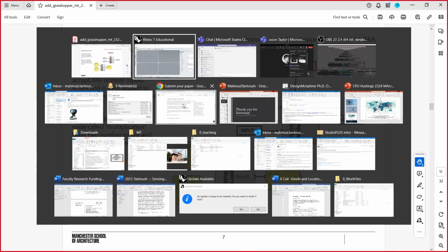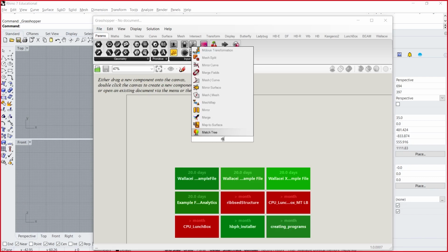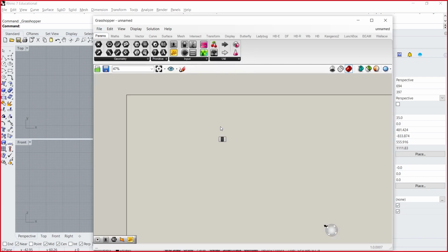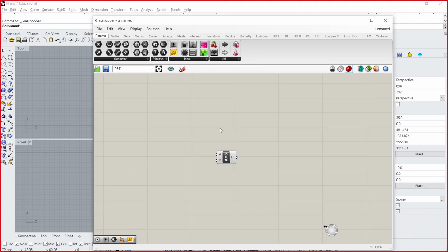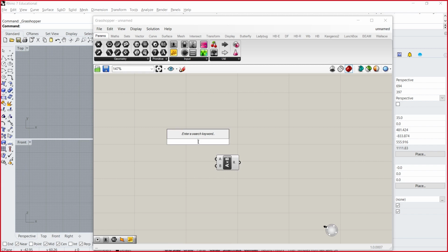So you can see here, yeah? Very simply. So I'll show you quickly here, just to drive it home. You can follow me if you want. So if I double click on the canvas, type in multiplication, and then double click again, type number 5, double click again, type number 5. You should have 2 sliders and one node. So double click on the canvas, type multiplication.